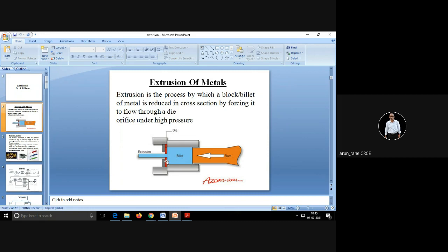And then it has to be hardened. Once you harden, your conventional machining process fails. So you need to do wire cut. You cannot finish the profile before hardening and then send it for hardening, because in hardening there are distortions, and the finish gets damaged. So what we do is rough machining by milling or any other process. Then we send the die for heat treatment, mainly for hardening, and then we do finishing by grinding, wire cut, or EDM.